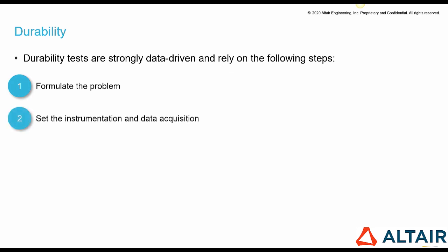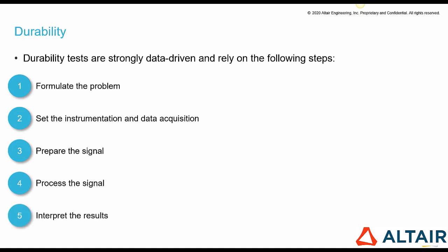Second, set the instrumentation and data acquisition. Third, prepare the signal. Fourth, process the signal. And fifth, interpret the results. And all these steps actively depend on signal processing to generate an accurate assessment of the component life.